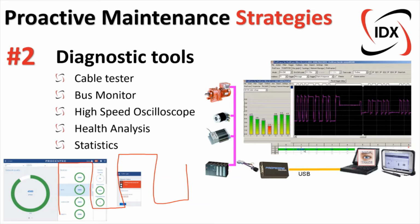And lastly, one thing PROFIBUS engineers love is statistics. Statistics are very useful to us to identify issues, whether they're from recurring faults or intermittent faults. Some of the statistics that we use when diagnosing PROFIBUS networks are things like syncs. A sync statistic is a counter where a PLC is programmed to communicate with a device, but the device is not available on the network. Whether the device is locked out, disconnected, powered off, or failed, a sync will indicate to you that the PLC is trying to establish communication, but that device is not there.